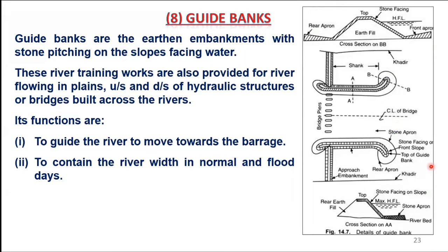Similar river training works are sometimes also provided in other hydraulic structures, like bridges which we build across rivers. You might have seen some embankments on the upstream and downstream sides of bridges. But the guide banks are the main component of the barrage.